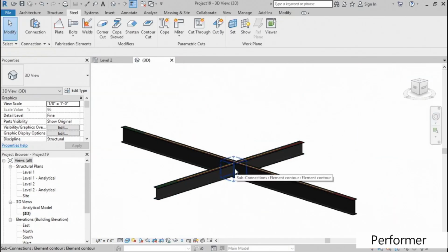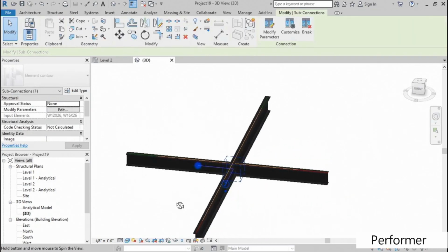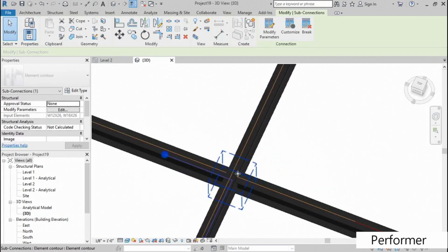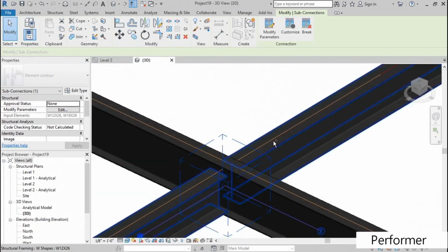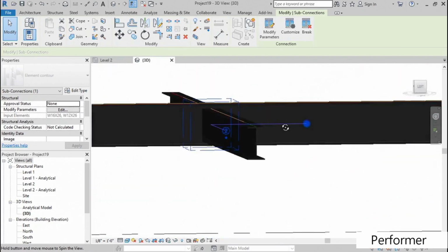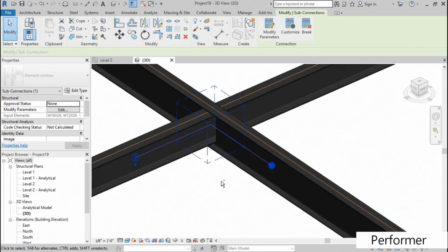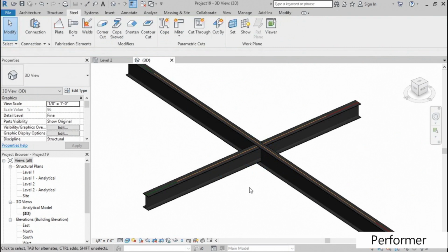If it didn't work on the first shot, what you need to do is select this. Then you can just change the direction that it's going in. But if this one is going to just basically slice it, it's going to be one beam, but it slices it, you probably never have that. So if I click this again, it's going to punch that hole through it. There you have it. Hit escape a few times. That's how you bore a hole through a beam with another beam.